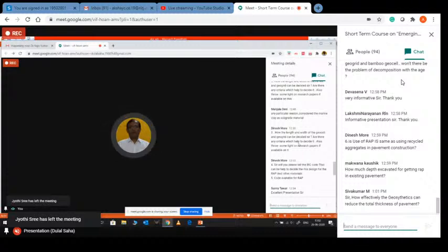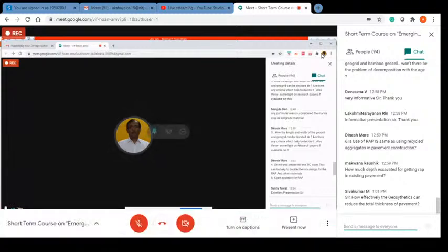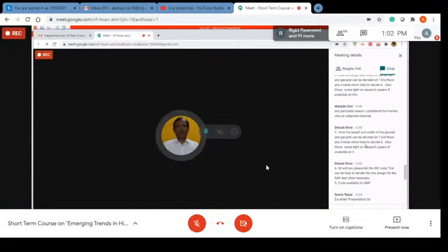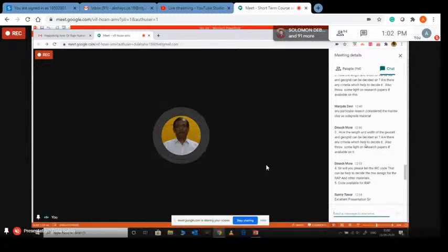And as it is a road of a little lower category in terms of traffic expected to be plying on it, to spend a huge amount of money just to improve the ground there probably will not be feasible. The objective is to cover more length, construct more length at lesser money. So the requirement is also less, that is, less heavily trafficked, a lightly trafficked road, and moreover it is in the remote area. So keeping these two things in mind, this was considered.